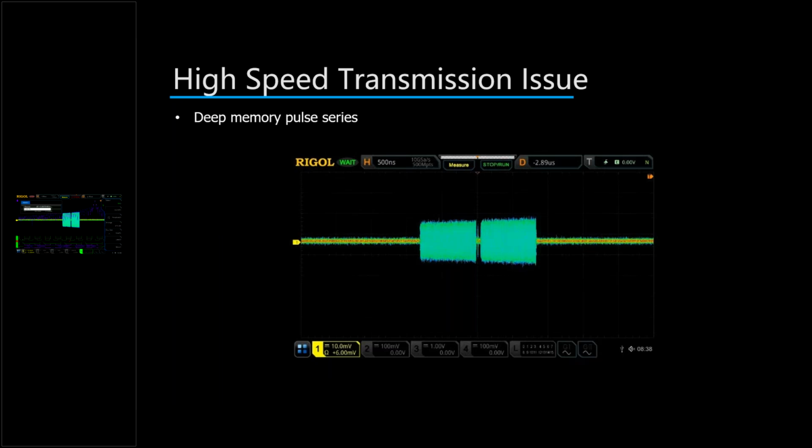So let's go back to the slides for a second. Again, we looked at those pulse sequences on the live instrument and those pulse failures. So combinations of occasional errors and glitches that we can really now dig into and resolve by doing high-speed time domain analysis of those, while also capturing them on the spectrum analyzer and pulling them down from that 2.4 gig carrier to a place where we can work with them.